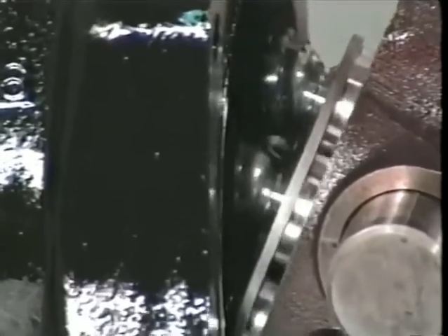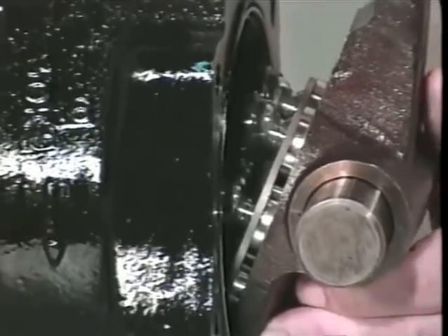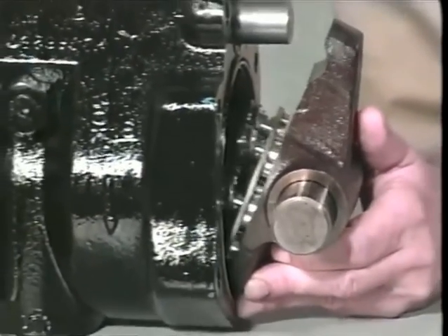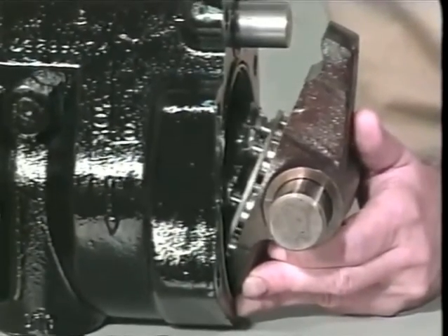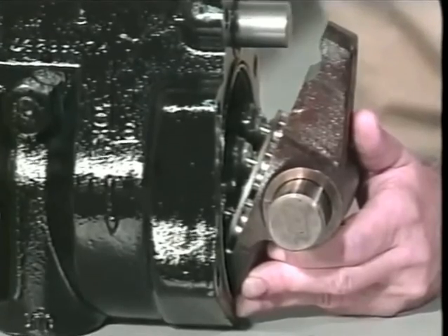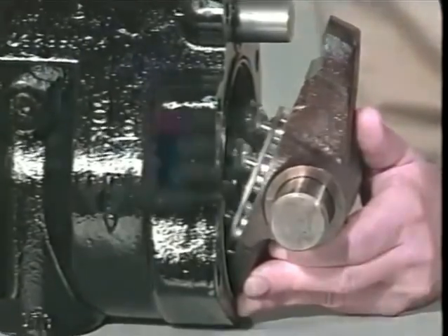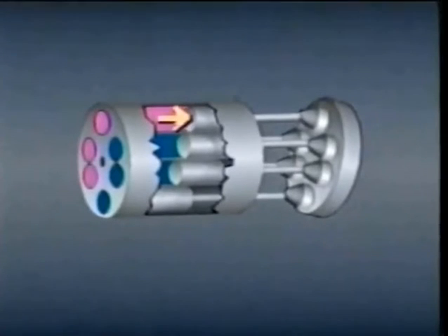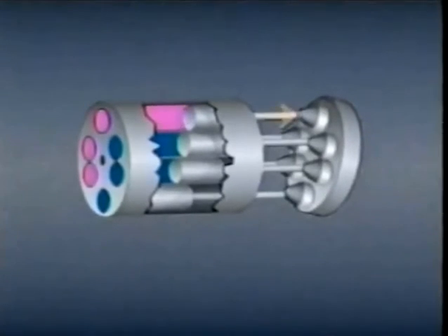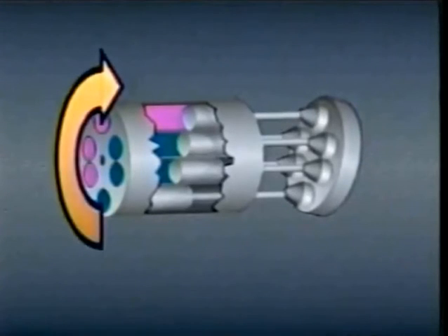After each piston passes the top of the swash plate, it starts back down, forcing fluid out of the piston bore and through the outlet port as the shoe and piston ride back down the swash plate. Increasing the pressure forces the piston shoes more firmly against the swash plate, increasing the torque applied to the cylinder barrel and to the shaft.